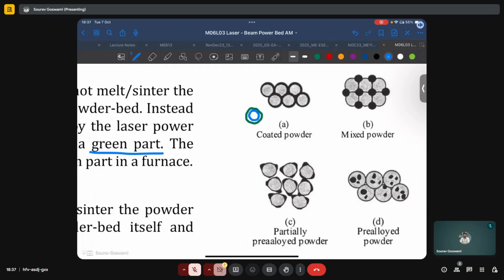Of course, it might be difficult because what can end up happening is if they have large powders or particles in one region, all the binding material or low temperature components segregate into a separate region, in which case this process will be defect prone. Or we can have partially pre-alloyed powders, alloying of course being a chemical change, in which case some of these low temperature components will be alloyed onto the metal particles, or we can have a fully pre-alloyed powder in which they are absorbed into the chemistry of the alloy itself and can be later liberated during the sintering process.